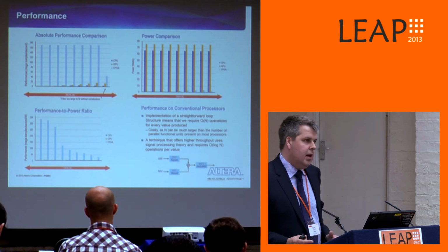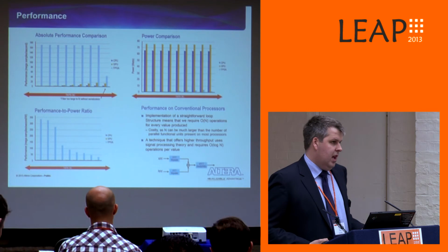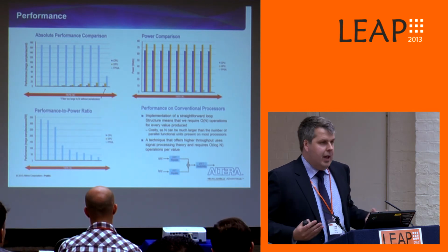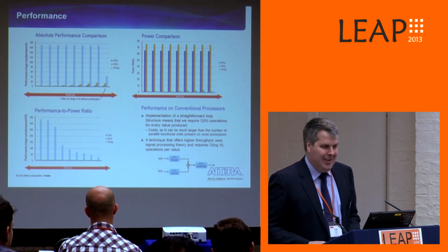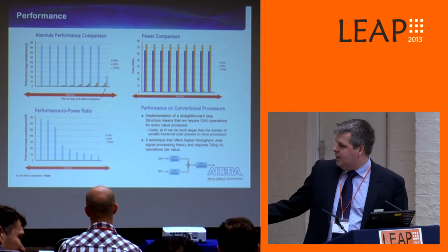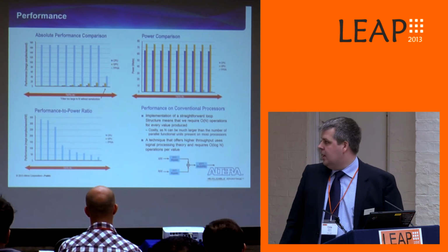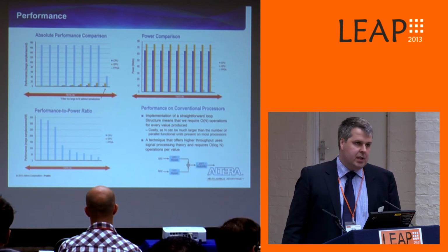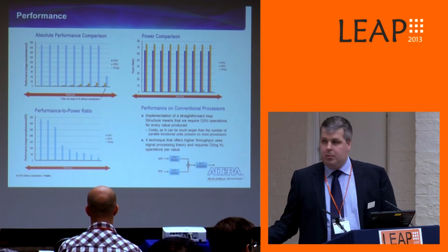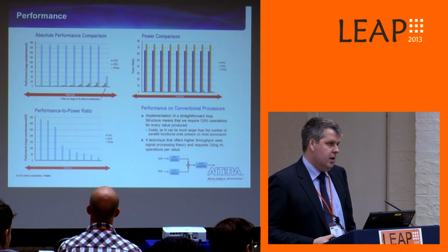Now, you could say this is a tailored application for FPGAs. Well, we could do that; we're marketing. We can actually try to implement that sort of benchmark. But what we did do was the signal processing that allows you to take this from an O(N) operation for a processor and turn it into an O(log N) operation, which is probably the most efficient way of doing that within a processor.